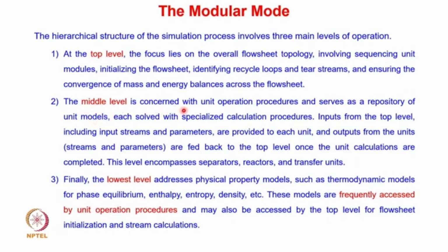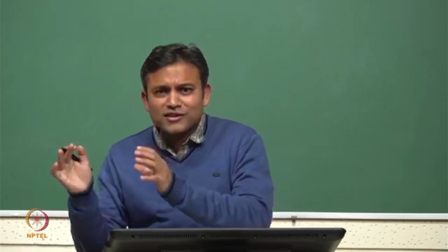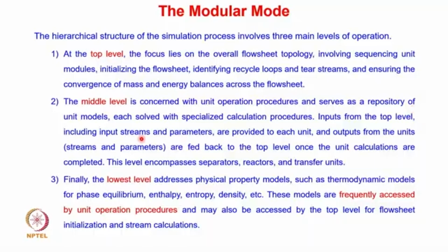The middle level is concerned with the unit operation procedures and serves as a repository of unit models. When we say repository of the unit models, what it means is models with respect to individual units are solved separately. In fact, if you look at most of the large scale plant designing, this is done mostly using the modular approach. You try to simulate each of these individual unit operations one by one in a sequential manner, isn't it? So a repository of the unit models is there, and each is solved with specialized calculation procedures depending on what inputs are there and what output you are desiring.